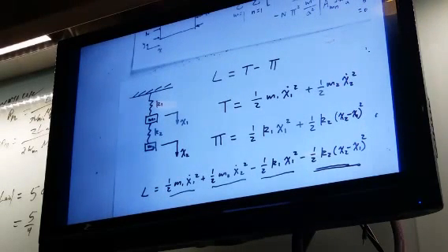Vibration analysis is different from all of the structural analysis we learned before. All of the things we learned before start with equilibrium. Total force is zero, total moment is zero. All of the equations we used, even for the buckling of beams, we start with the free body diagram, the equilibrium of each segment. But for dynamics, for vibration, we have an inertial term to worry about. So it's not just simple total force is zero. Total force should be equal to m times the acceleration of the system.